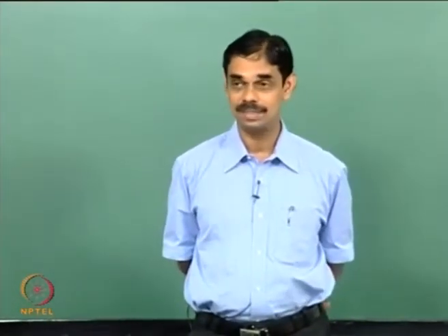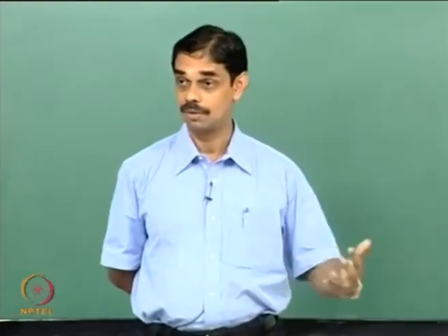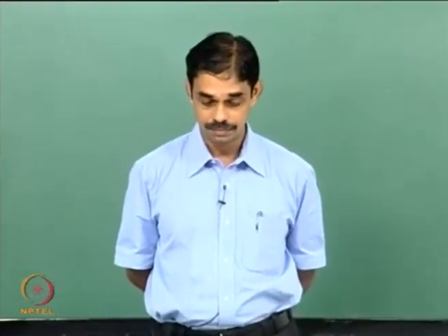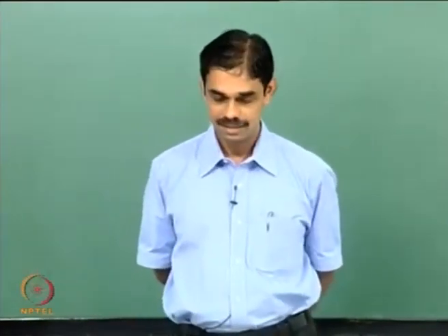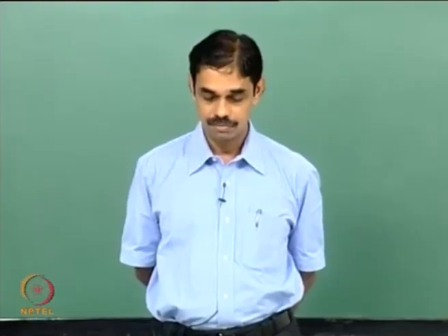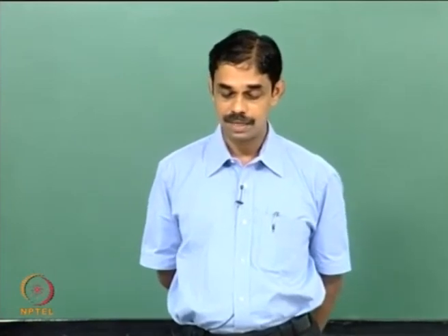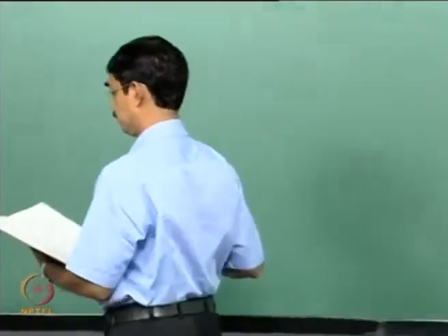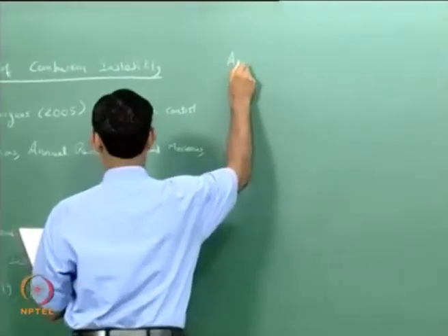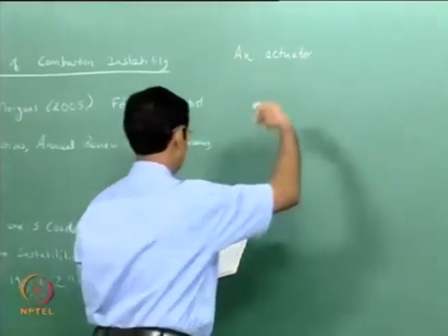So the other possibility is active feedback control, or active control of combustion instability. So here, as opposed to passive, we actively meddle with things and actively try to disrupt the coupling. We have an actuator which modifies some system parameter in response to a measured signal. So this is the crux of the active control. Again, you can have many actuators, but I just write it symbolically.